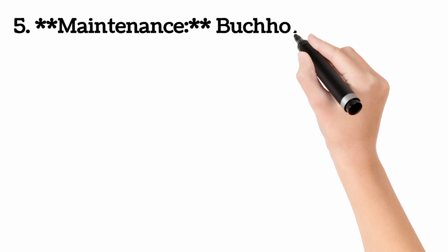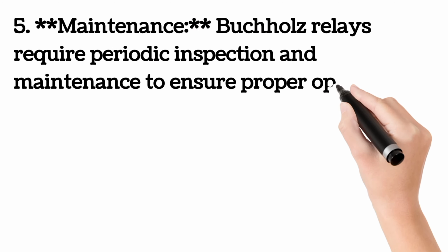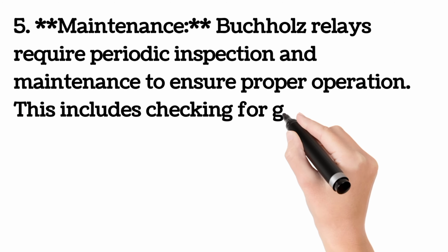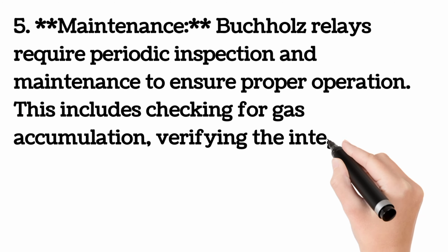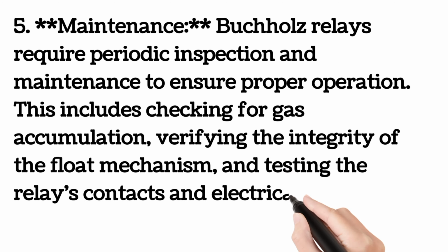5. Maintenance. Buchholz relays require periodic inspection and maintenance to ensure proper operation. This includes checking for gas accumulation, verifying the integrity of the float mechanism, and testing the relay's contacts and electrical connections.